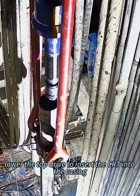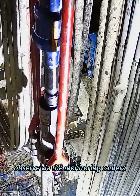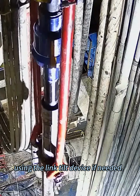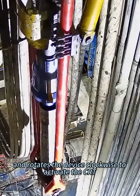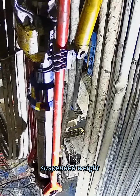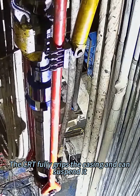Lower the top drive to insert the CRT into the casing, with the anti-collision plate resting on the casing collar. Observe via the monitoring camera and adjust the casing position using the link tilt device if needed. The driller applies downward force and rotates the device clockwise to activate the CRT. Continue rotating while maintaining the top drive's natural suspended weight. When torque exceeds 4 kN, the CRT fully grips the casing and can suspend it.